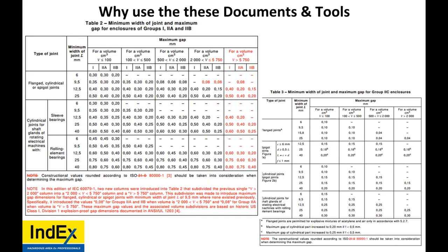Why is there an Ex d conduit if they are bearing an ATEX certificate, connecting the joint to Ex d equipment? How is the inspector to determine? So for a conduit, they need to have a barrier within 450 millimeters, 18 inches. So the conduit is a wiring means. It does not need to be certified with the equipment. Under explosion proof, it does. How does the inspector determine this?